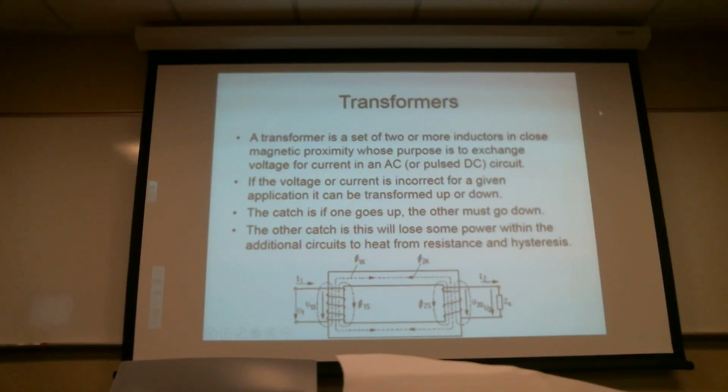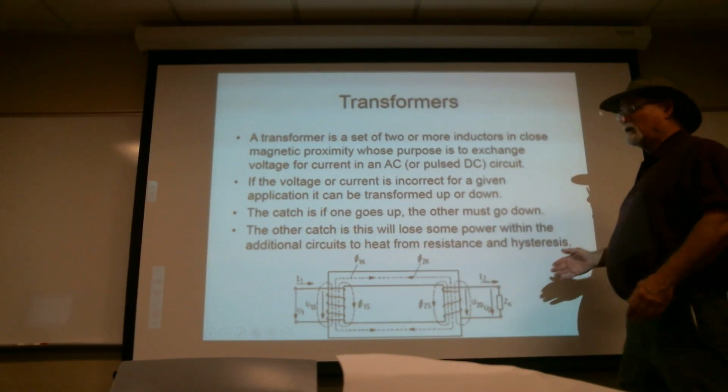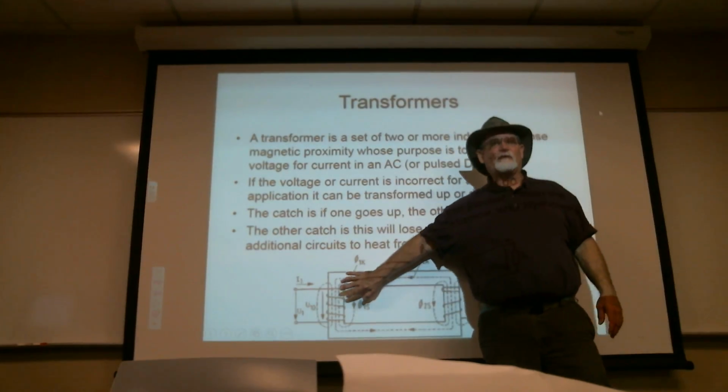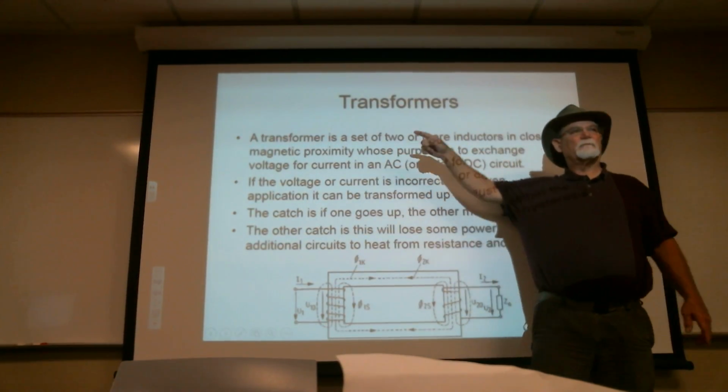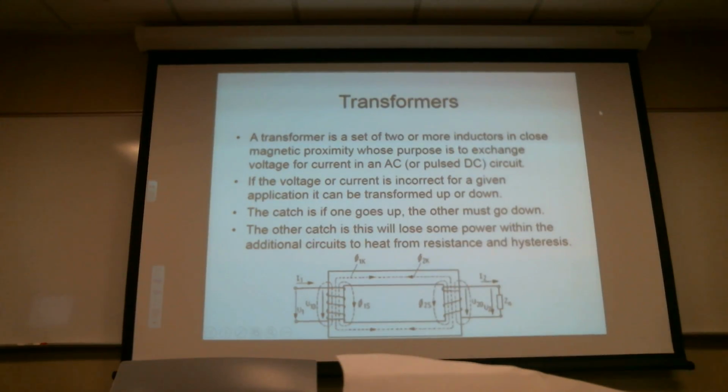There's one exception to that. There are times where we will use this thing not so much for the sake of shifting voltage up or down, but because this is a little bit dirty. Instead of being a nice clean sine wave, it's got some noise in it. It's a little bit imperfect. The magnetic field can't move fast enough to make all of those little imperfections translate into the magnetic field. So what will happen is this will put the same amount of voltage and current out in the same form, but it'll be a lot cleaner. So in that case, we're using it just to filter.